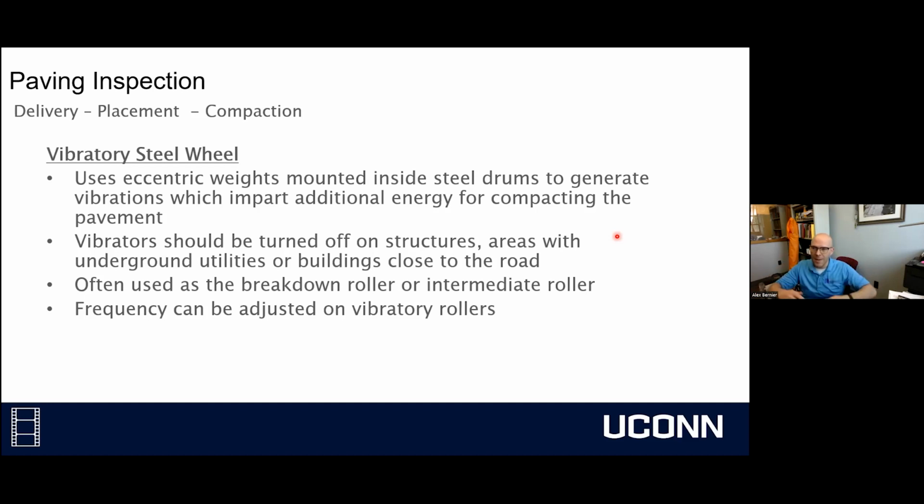And it's actually picking up the drum and dropping it. It's making it jump on the pavement. And you can imagine that doing this imparts greater compactive effort. It's going to be pushing more down on our pavements. There are some challenges with this, though. If you're vibrating too much, you can cause the material to move.